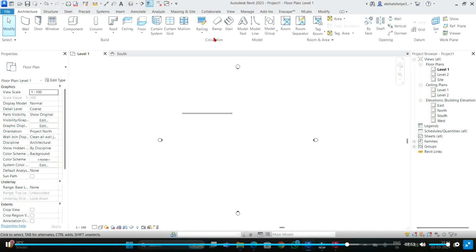It might become so on a large scale. So what we have to do is try to reduce the load on it so that you can work smoothly. One of the ways of doing it is working in hidden line and shaded mode. That's one thing we need to keep in mind. And whenever you're working on projects, work in fine mode. It gives you much more precision. Clear?